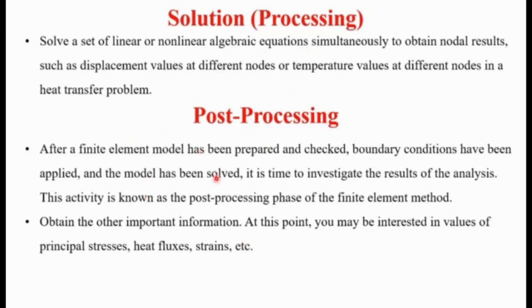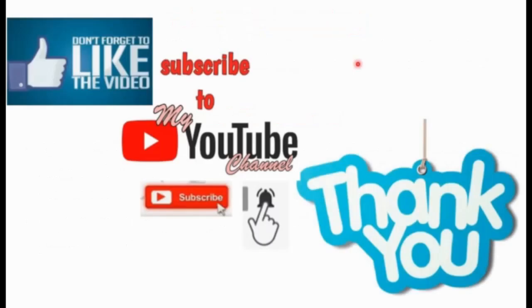In the post processing phase, we will get the other important information, for example additional information that we want to estimate or want to know. Then at this point again, you may be interested in the values of principal stresses, heat fluxes, strains, etc. So that we can calculate in the post processing phase, the third phase of this finite element analysis. This is the third phase of FEA.